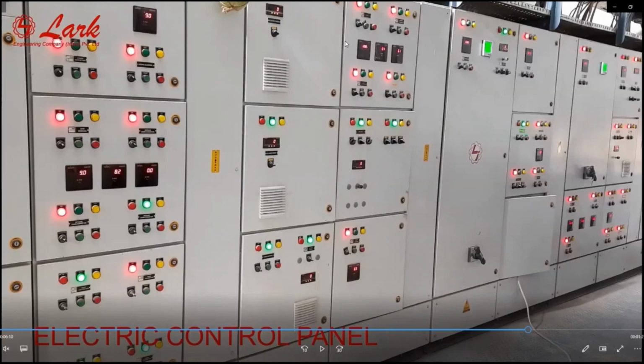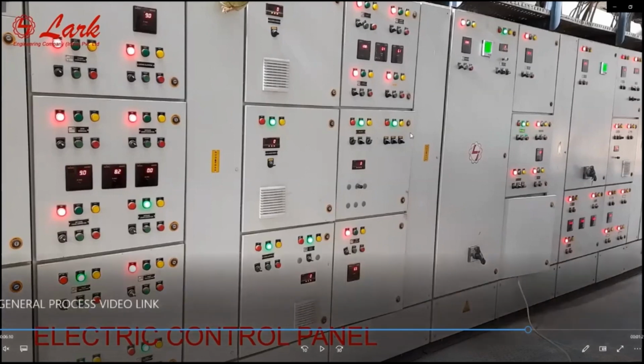So we have to check whether the hammer mill is running ideally or consuming idle power with respect to the production, or the pellet mill is performing poorly with respect to efficiency and power consumption. So we can add the energy meters even in the existing panels with the help of our electricians to monitor the power consumption trend of our machines.